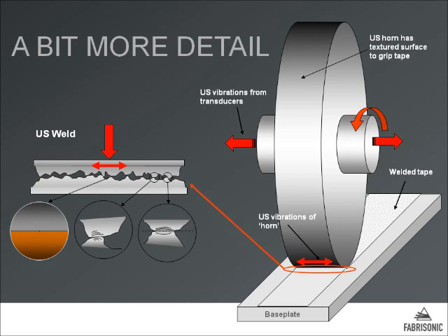Now the question is always asked, what happens to that oxide layer? Well, unfortunately, the oxide layer isn't totally destroyed. It's still there in the bond. We typically see it as small particles or gravel inside a micrograph, about 150 microns either side of the bond joint. And this does have an effect on material properties.